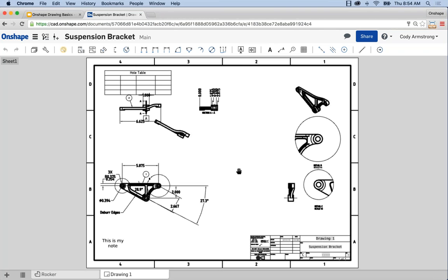All right. Now, we've mentioned many different things about creating drawings, but what about getting into more detail about using my own templates or importing and exporting? I've already briefly shown you that you can import anything. And again, the command to import, you'll find it under Create tab. You select Import, and you can browse to any DXF, DWG, or any number of different 3D formats as well, Parasolid, Step. So remember, you can import anything into a document. You can even import Excel files and images and just store them as a tab within the document. But this is how you import. Browse to your DXF, DWG, and it imports as a tab into the document.